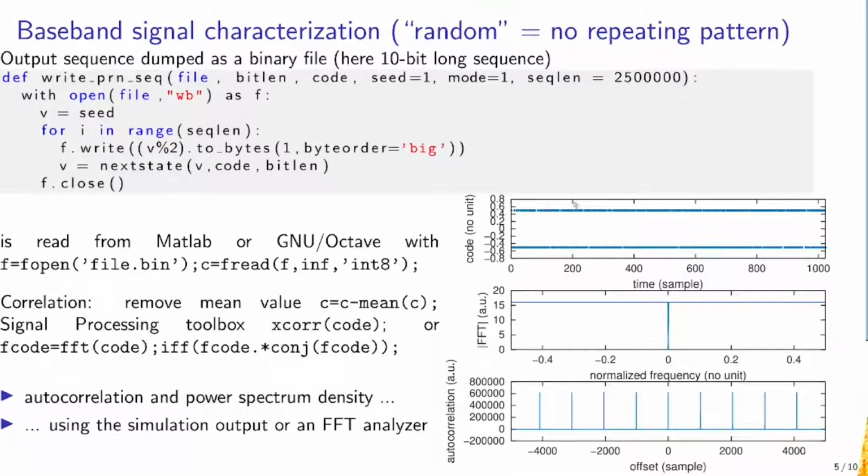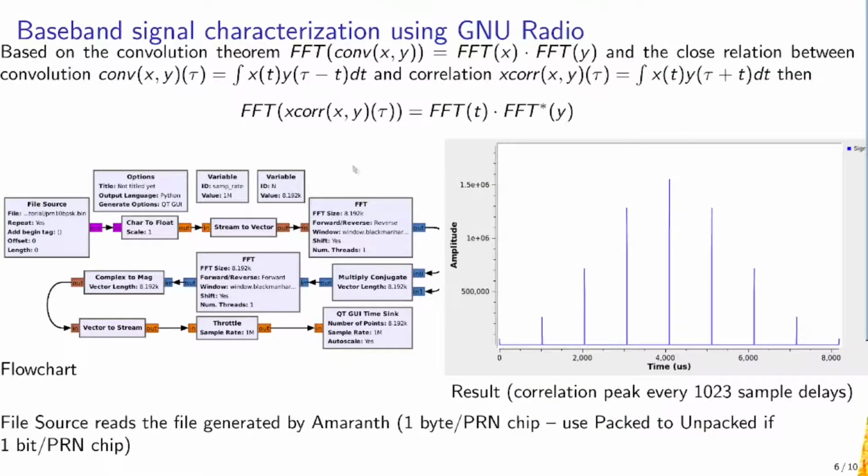So now that we're finished with the analysis of the baseband signal, and that we're convinced of the capability of GNU Radio of computing a correlation through the product of a Fourier transform, as we've just done, we've linked the radio frequency signal synthesis from the FPGA into GNU Radio, and now we wish to go to the next step, namely modulation and transposing the signal to the radio frequency band.